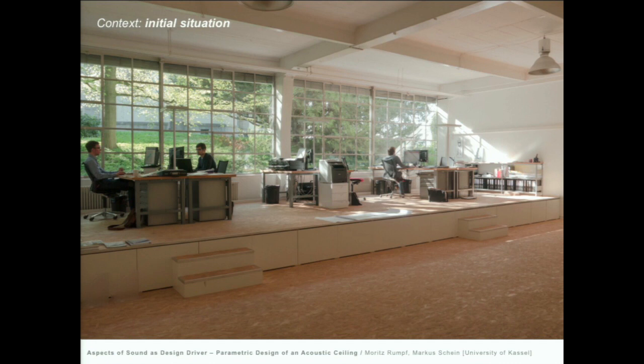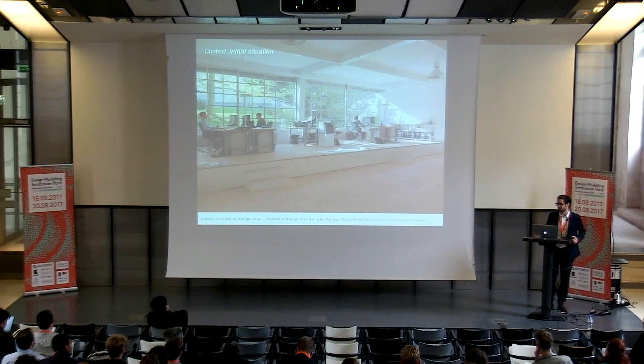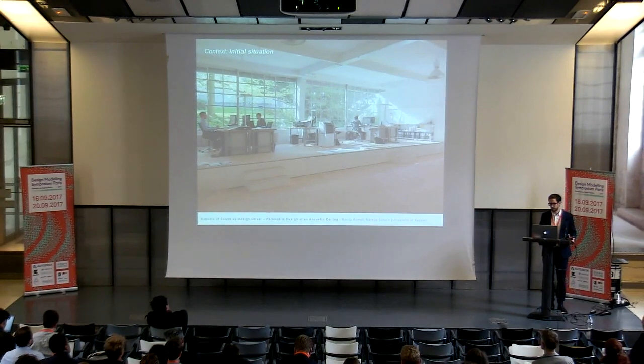The design location is the Office of Design to Production in Zurich. It's a box-shaped office with primarily hard, non-absorbing surfaces, and even the furniture has almost no sound-absorbing material. So the audibility was clearly perceivable as being poor, impeding and hindering communication. I think you can ask Silvan, who presented yesterday, about that. This was also confirmed by a measurement of the reverberation time, which was approximately 1.3 seconds on average.